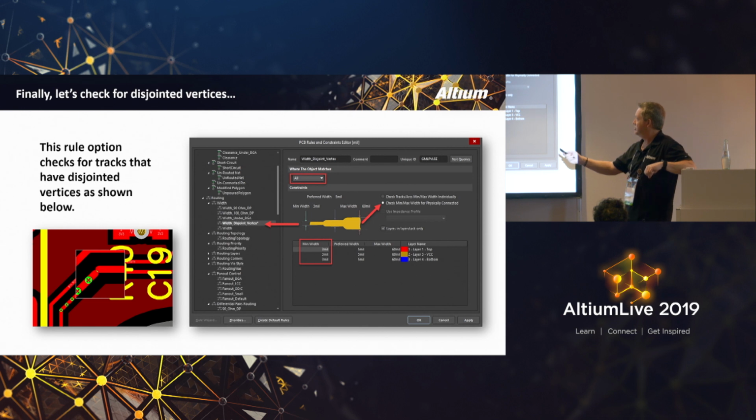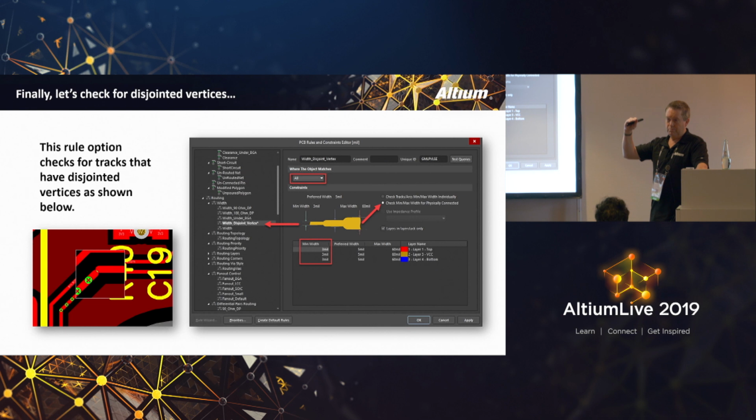Now here I've got the clearance right above the minimum clearance, so it's filtering down and hitting that rule. But since that is a unique rule, I could raise it. Well, do you know what? I do have to have it underneath my differential pair rules, because in my differential pairs I have to route at least at 3 mil width to get under the BGA. So even at the bottom of the list, it is abiding by the 3 mil rule for those differential pairs. I think if I had this rule prioritized higher, above the 90 ohm differential pair rule, then it would cause me some problems.